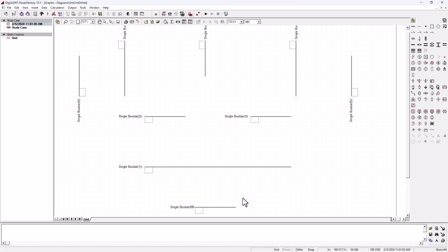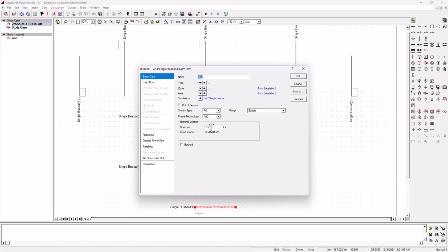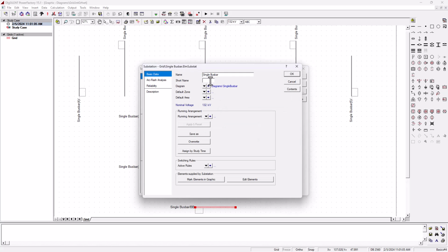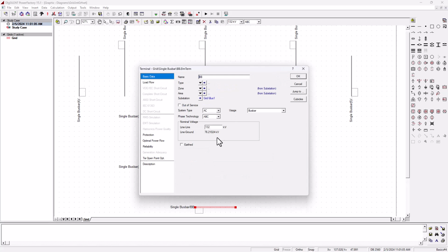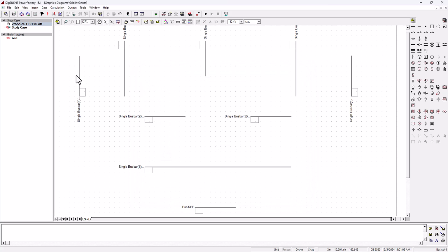So to set up your bus bar voltage, let's go ahead and click the bus bar and click on substation. There are many ways to do this, and we're going to give it a short name, bus 1. The nominal voltage is 20 kilovolt for bus bar 1, the slack bus. Yes, move to bus bar number 2.